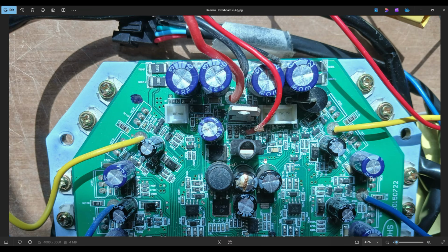R is like the decimal point. Its purpose is to measure the current through the voltage drop, and it is a standard hoverboard value. There are two R007 in parallel, on two phases. If you know Ohm's law, you can read how it works.